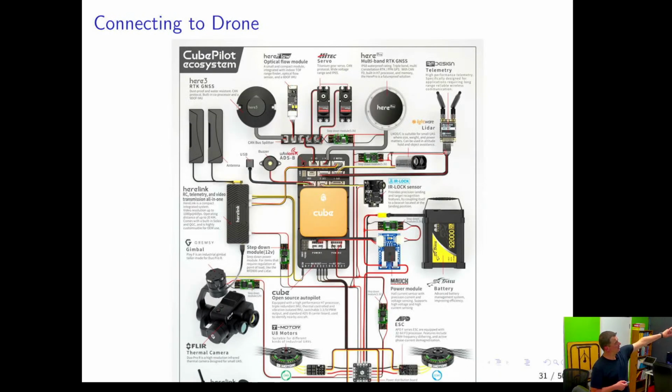either way, you can see how it connects. I'll just go over a few of these. But the motors, I don't know if you guys can see these. The motors are down here. It just has two, and they're connected over a PWM interface into the autopilot with a cable each. Then they have some things connected with I2C, and then the CAN actually is up here.